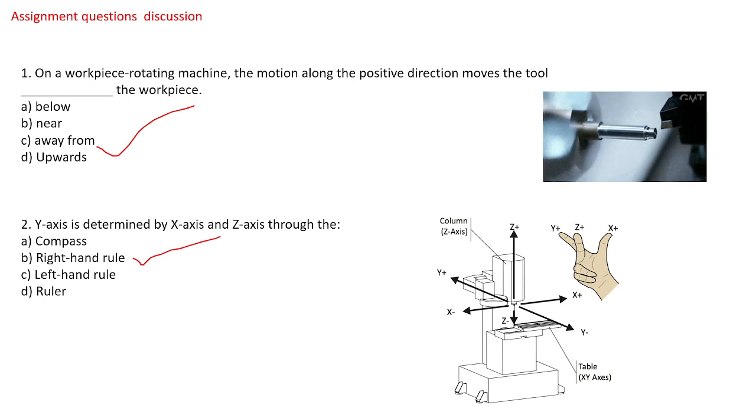composites and also very thick plates, because laser cannot cut beyond 25, 30 mm. I have not seen any machine cutting more than 25, 30 mm with laser cutting. That's particularly true for CO2 lasers.